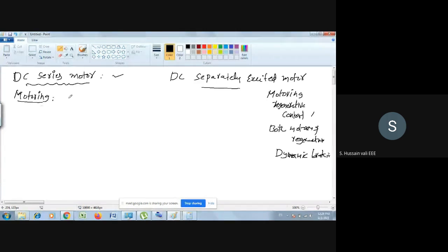You recall that this is EB. For the motoring, we are drawing the circuit diagram. The chopper circuit diagram does not change, only the motor will change. Now, how is it different from the previous case? That is, this is RA plus RF. The series motor has both.